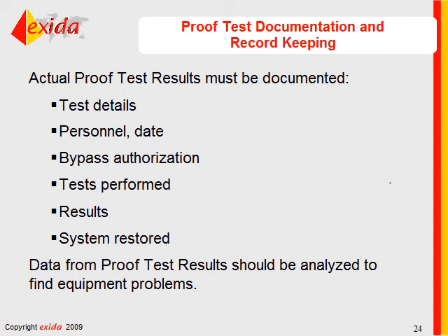Now, another situation that I've seen in the past is where there was a master fuel valve where it basically determined that a proof test needed to be performed every year. However, operations did not want to shut down every year, and in this particular case, a bypass valve was installed that was normally closed, and that would be opened once a year when the proof test was done on the main fuel valve.